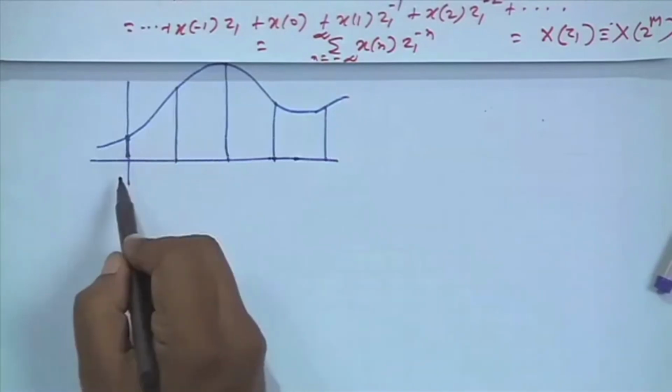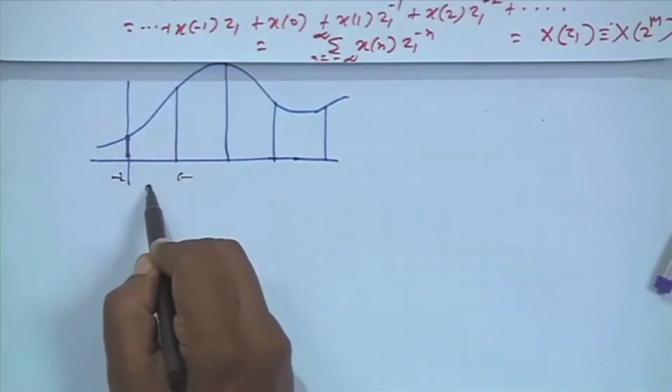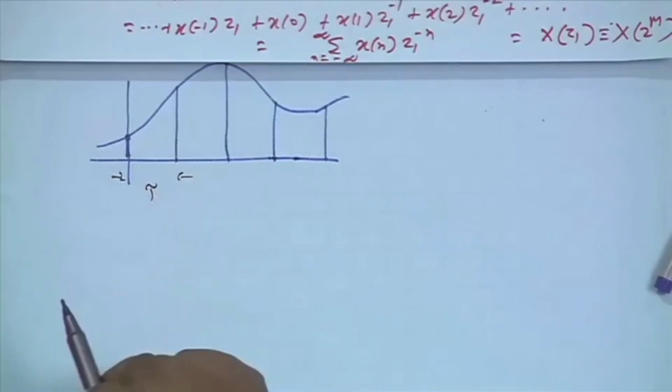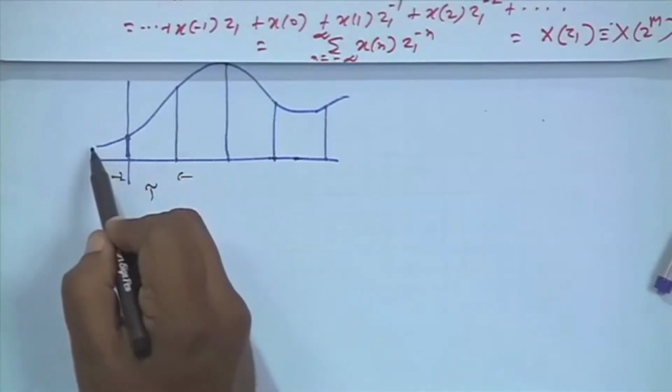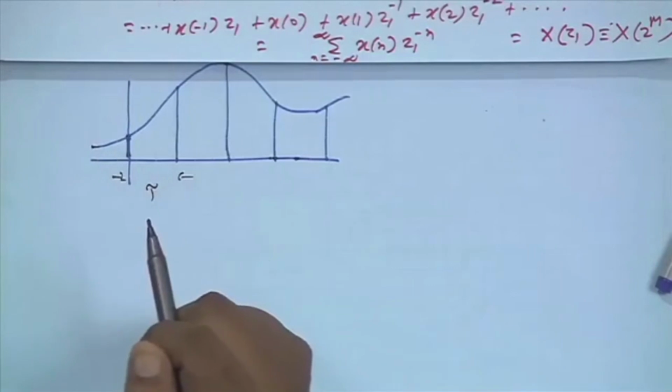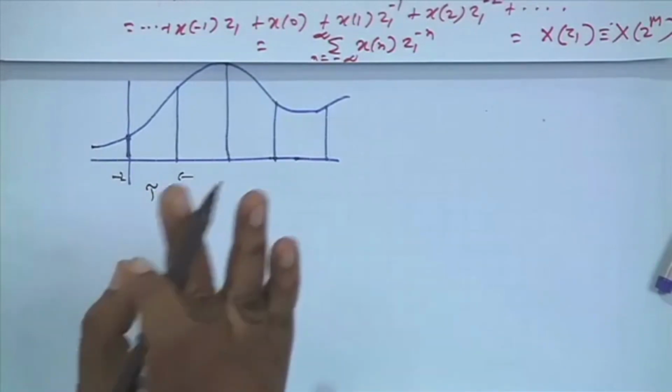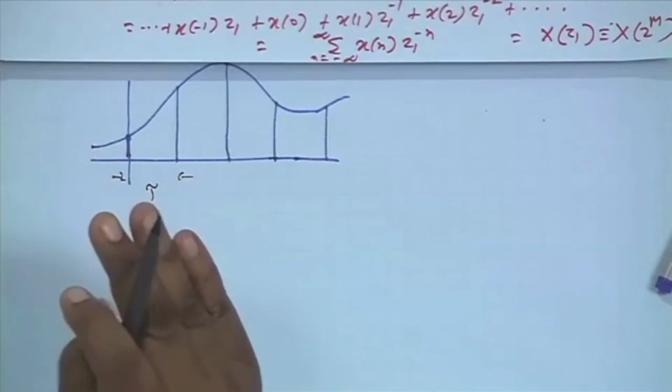Okay. So much was my sampling period tau. And this is done taking care so that Nyquist rate is not violated. I mean, we are above Nyquist rate, even if the sampling rate is not high, this is good enough. We are above Nyquist rate, there is no aliasing and all that. Now, my question is, if I employ a higher sampling rate, of course, I am doing better. Instead of falling below Nyquist rate, I am going further above, so no question of aliasing.